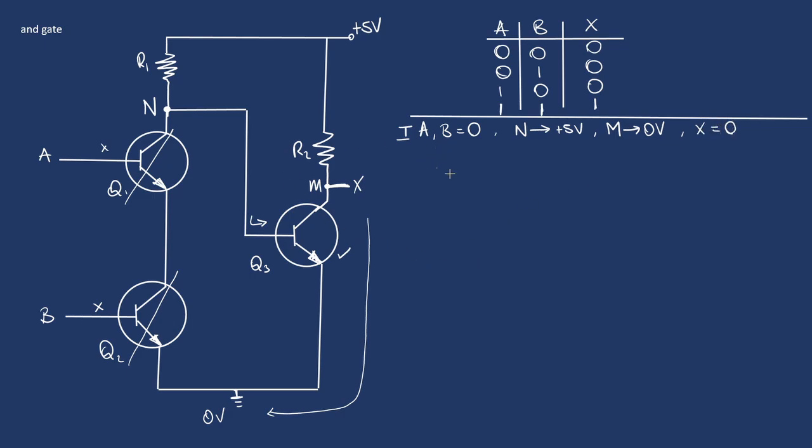Okay? It's very simple. So Q1 is off. Q2 is off. And Q3 is on, because there's current flowing into Q3. So that's how to understand the first case of the AND gate. A and B are 0. This is 0. This is 0. No current enters IB. No current enters IB. This guy stays turned off. This guy turns off. N is a floating node.